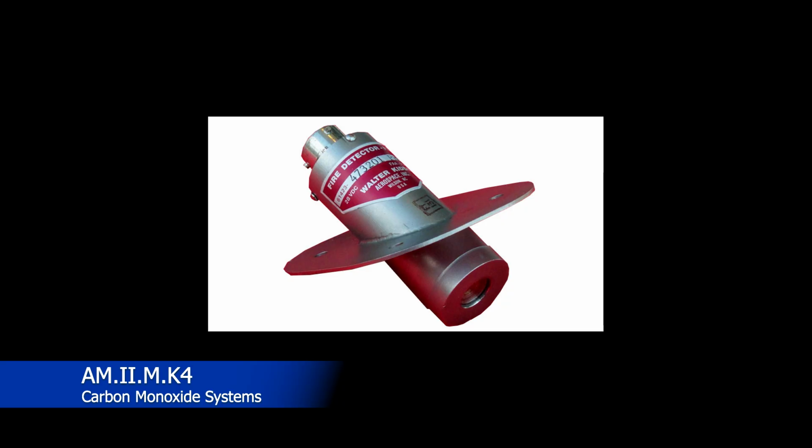IR-based optical flame detectors are used primarily on light turboprop aircraft and helicopter engines. These sensors have proven to be very dependable and economical for those applications. Now, when radiation emitted by the fire crosses the airspace between the fire and the detector, it impinges on the detector's front face window. The window allows a broad spectrum of radiation to pass into the detector where it strikes the sensing device filter. The filter allows only radiation in a tight waveband centered around 4.3 micrometers in the IR band to pass to the radiation sensitive surface of the sensing device.